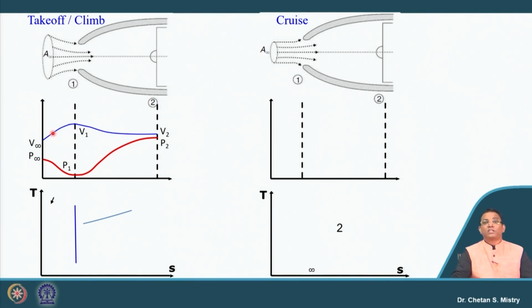Now let us look at what is happening with my total pressure. Here this represents my total pressure condition. My total pressure remains almost constant, and then I will have a slight drop of pressure. We know the reason: because of the presence and growth of my boundary layer, the skin friction losses come into the picture.